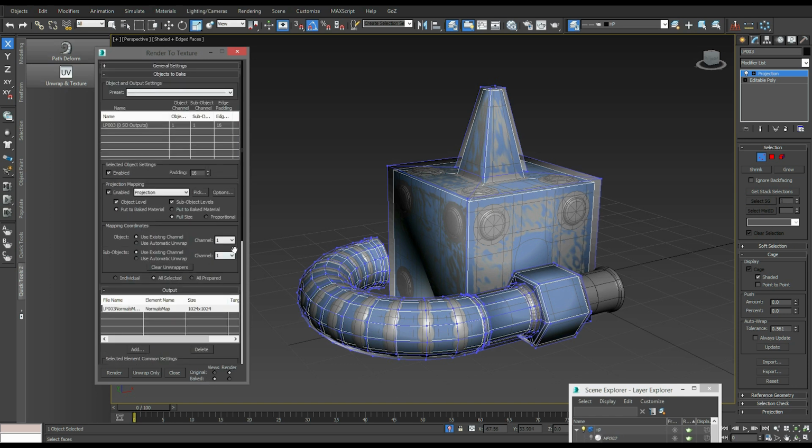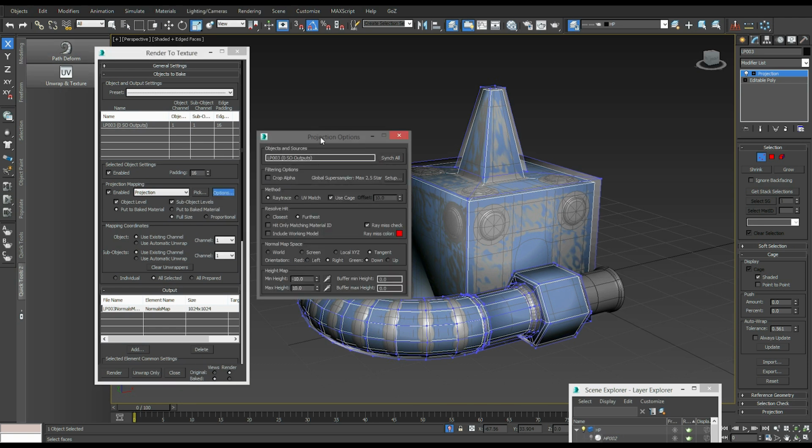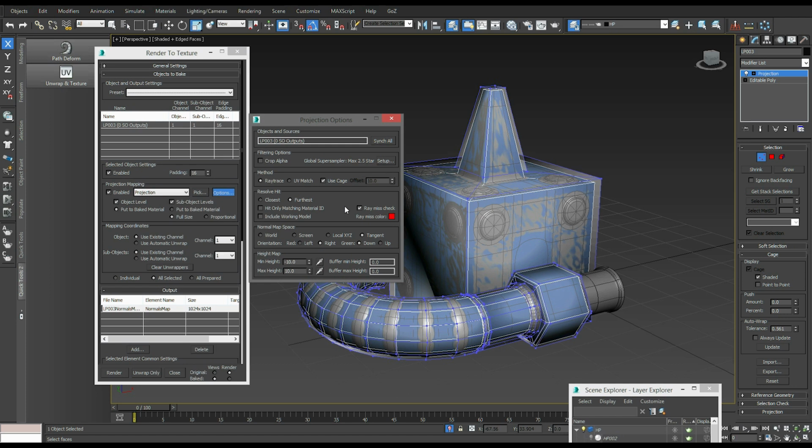And then the next part I want to talk about here with the box, the rollout here, is under options. We're kind of going back to here. Under normal map space, one of the most common settings for doing normal map baking is flipping the Y channel, or the green channel, up or down, plus or minus, and it just depends. Max, for example, is default Y negative, and that's why this is on down right now. This is where you're going to set the normal map to either Y positive or Y negative. I normally work in Y up because the Toolbag is like that, and I just stay in that, but whatever you want to bake out to is fine. So, I'll just keep it at down for now because this is fine for what we're doing.